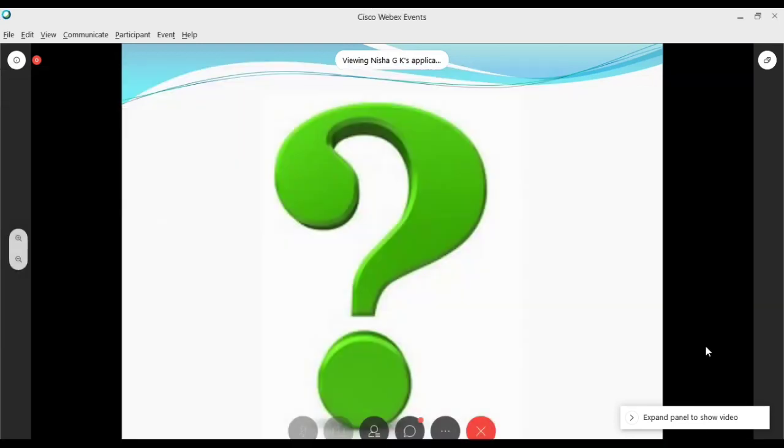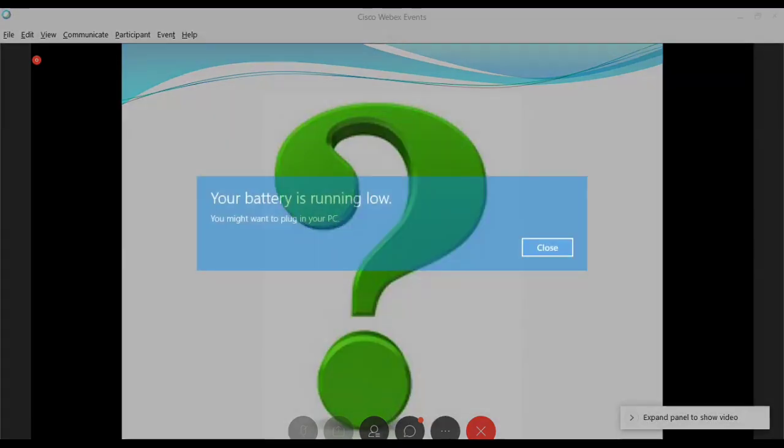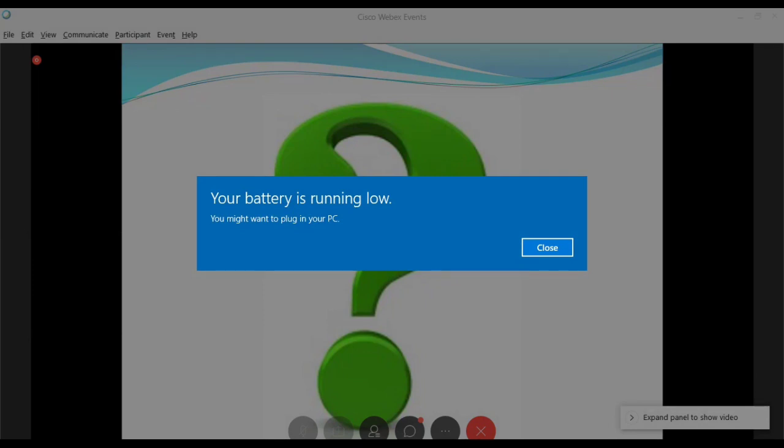And instead of that, for speed control techniques, you can use inverters also. You can use a chopper fed current inverter, or different AC fed converter systems, to control the speed. You will have the thrust and the speed as the input, and you can have the inverter with a switching sequence. Then you connect the linear induction motor, and you take the speed corresponding to that. You can feed it back and control it as a closed loop, and then you can control the speed of the motor. Okay. Next question is from Karthik.